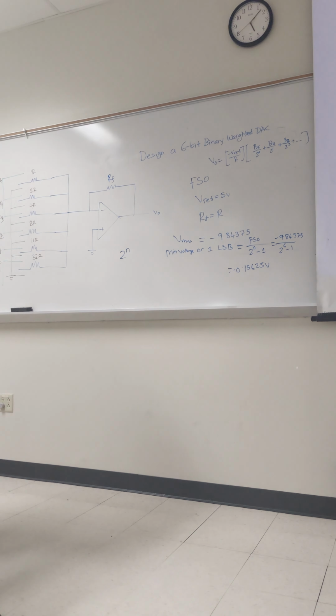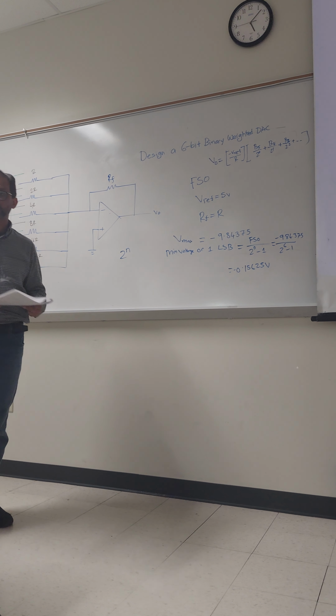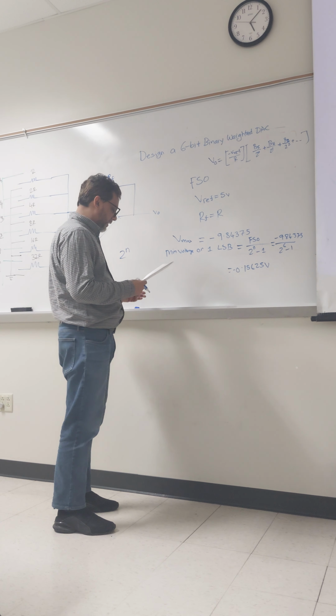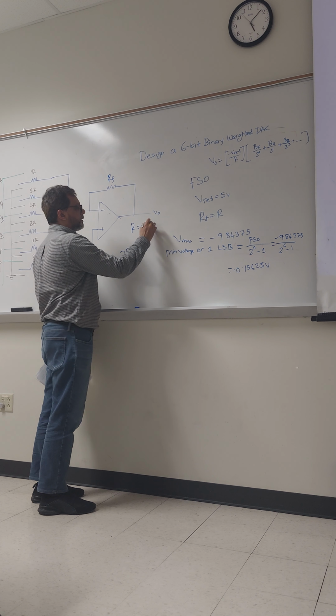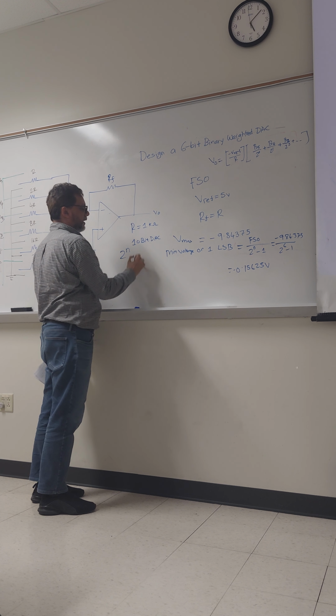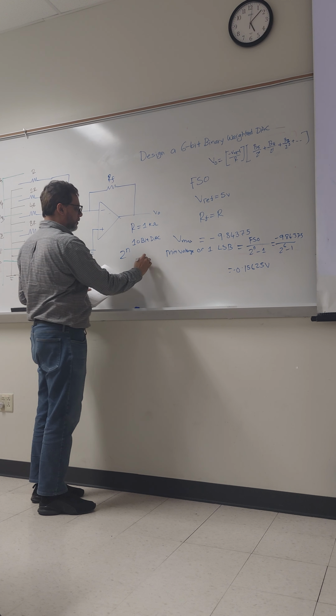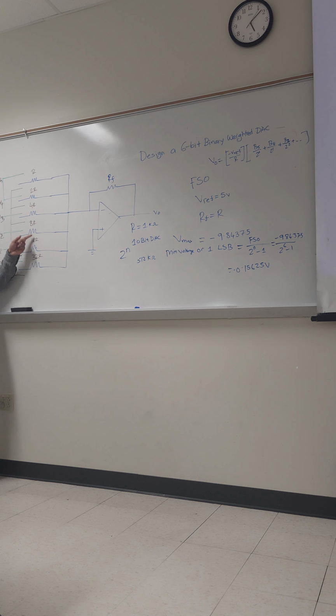For example, for a 10-bit DAC, it requires around 512 kilo ohm resistance. If we just think that R equals 1 kilo ohm, then for a 10-bit DAC it requires 512 kilo ohm resistance. That means you need to decide precise resistance values every time, so it is not always possible. That's why, to overcome this, we have another technique for DAC known as the R2R ladder circuit.